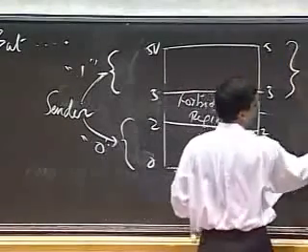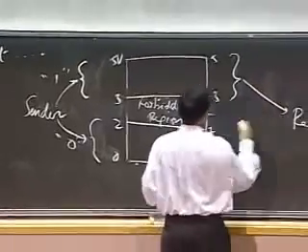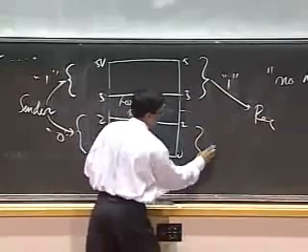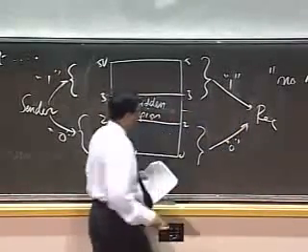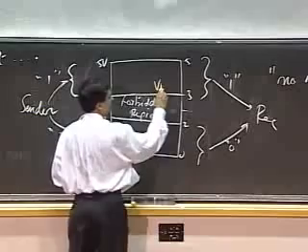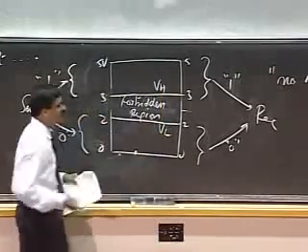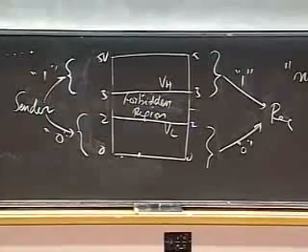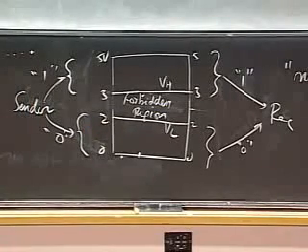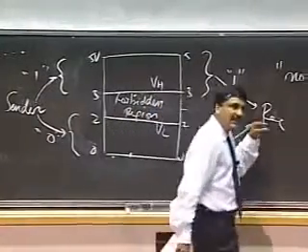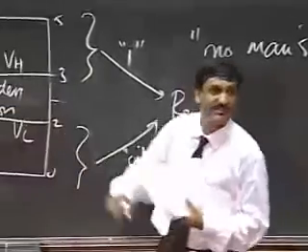At the receiving side, if I see any value between 3 and 5, I read that as a 1. And any value between 0 and 2, I read that as a 0. So I may label this threshold VH and label this threshold VL. So there's a high threshold and a low threshold. So this solves one problem. Now, the receiver can never see a value in the forbidden region.